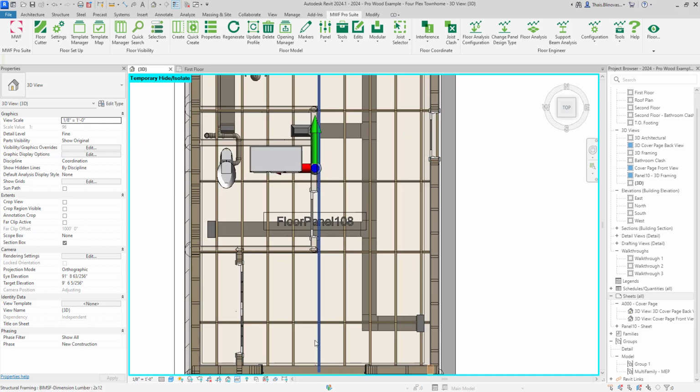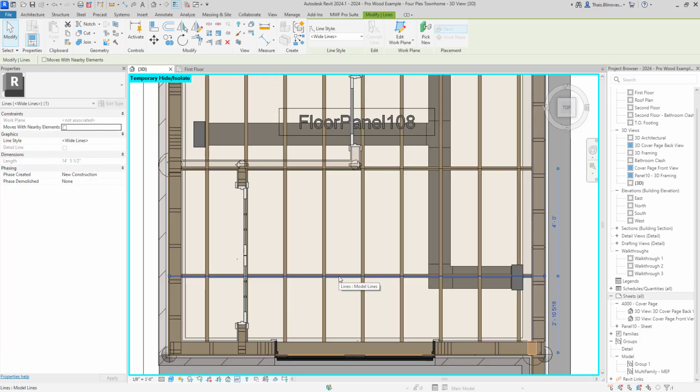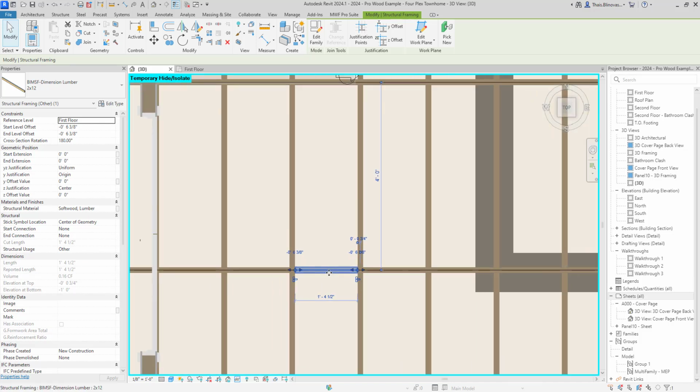And as you can see, it does have a few blocking. So this blocking was added with the marker lines. Again, with floor panels or ceiling panels, we can only generate blocking or punches with marker lines. So before, we wouldn't be able to use any edit commands with these that are generated with marker lines. And now you can actually use either move generated or edits one to make small modifications here, and it will remain after regeneration.